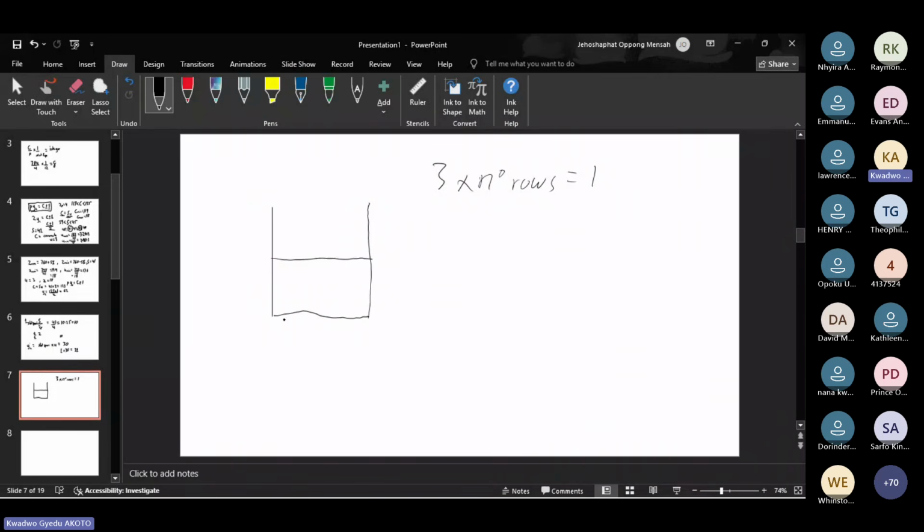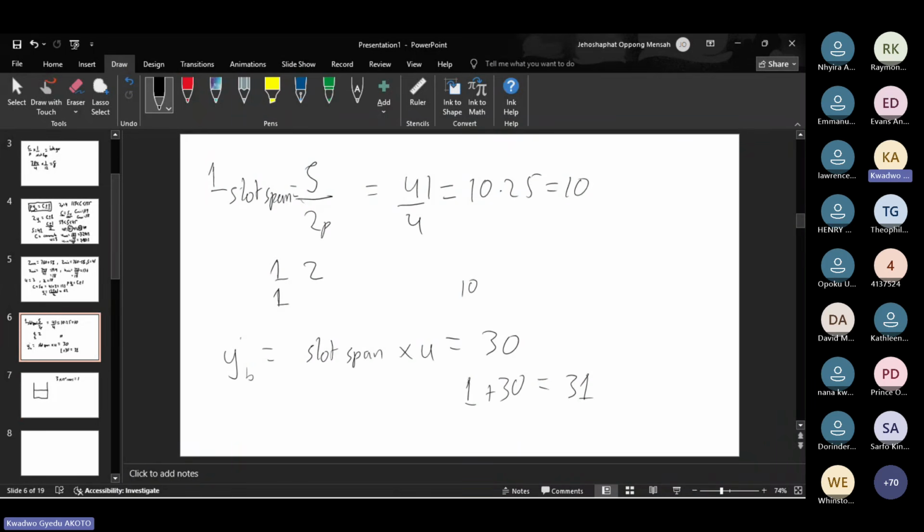Question E says, determine the number of bottom conductors for coil 1 if its top conductor is given the number 1. We know that for a machine, if our top conductor is in a slot here, the bottom conductor making up that coil is going to be in another slot, here. So this is how our coils look in a machine: top conductor here, bottom conductor here.